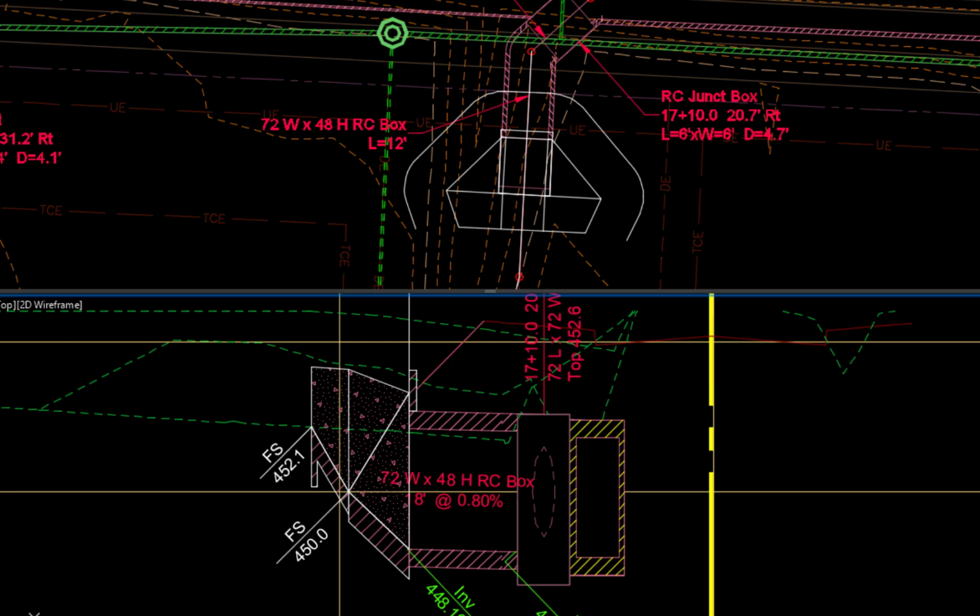of the surrounding 3:1 earth and slopes. The head wall, wing walls, and concrete slope paving are drawn in plan view. At this location, the side slope of the concrete paving is 3:1 and the height above the channel bottom is 2 feet. The top of slope will be at a horizontal distance of 6 feet from the bottom. At this location, the side slope of the concrete paving is 2:1 and the height above the channel bottom is 4 feet. The top of slope will be at a horizontal distance of 8 feet from the bottom.